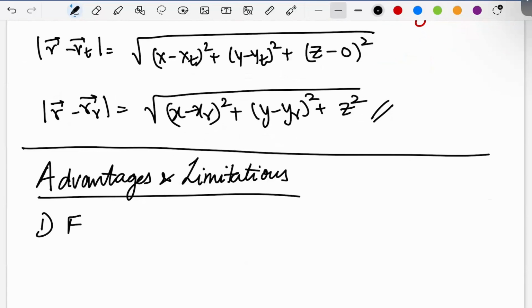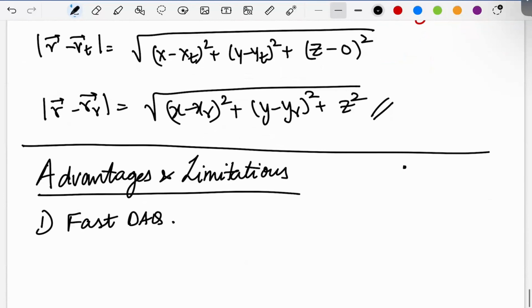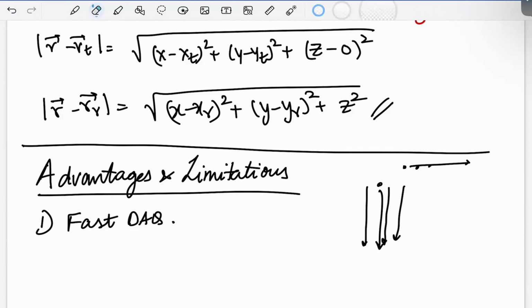So the big advantage is that it's very fast data acquisition, right? Assuming you have an actual aperture, you can also do MIMO as a synthetic aperture. You can place the transmitter and receiver on two linear stages and move them, but you don't really get any speed improvements, because you have to stop the transmitter, collect all the receiver positions, then move the transmitter, and again collect all, then move, then again collect all. So typically MIMO is not done as a synthetic aperture.